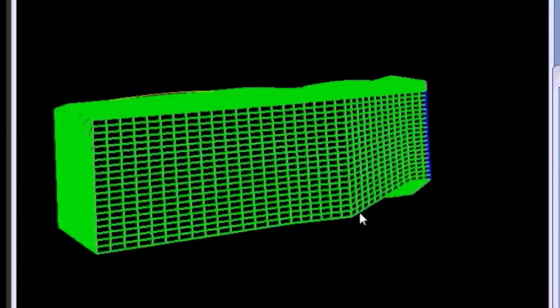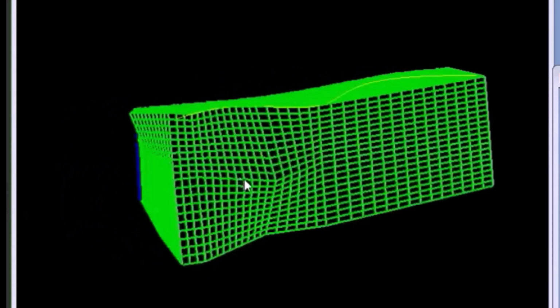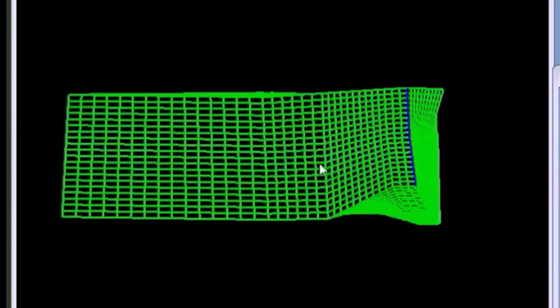And now you look at this block and you think it's not 6 different blocks, it's just one. We've essentially erased the block structure of this region of the mesh by using interpolation. And I get a much smoother mesh. I can't have that smoother mesh here because I'm going to have to place it along a curve. But this side can be freely interpolated.